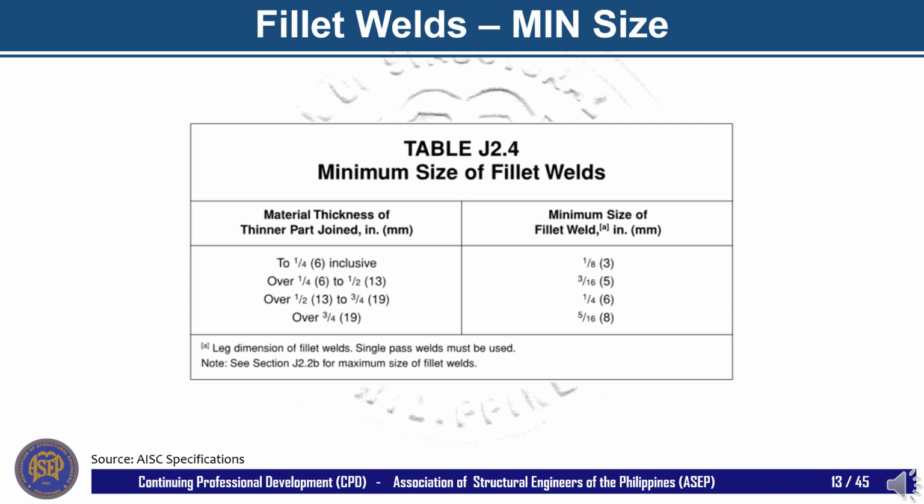To make a good arc weld, a minimum amount of thermal energy must be introduced into the joint. Failure to do so may result in the deposition of weld metal without fusion to the base metal. Otherwise, when insufficient thermal energy is delivered to the joint, the cooling rate experienced by the weld and the heat-affected zone may cause some cracking in the connection.